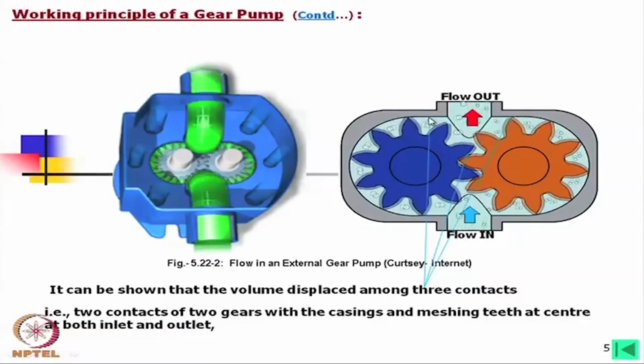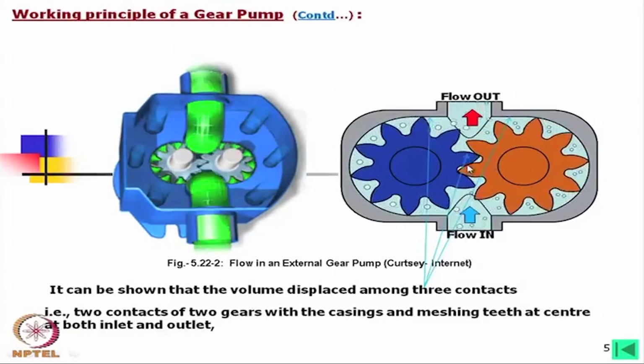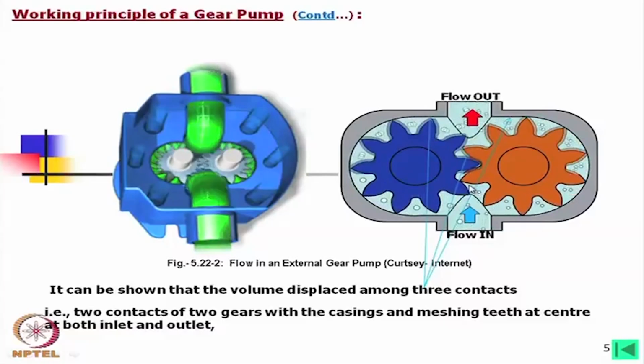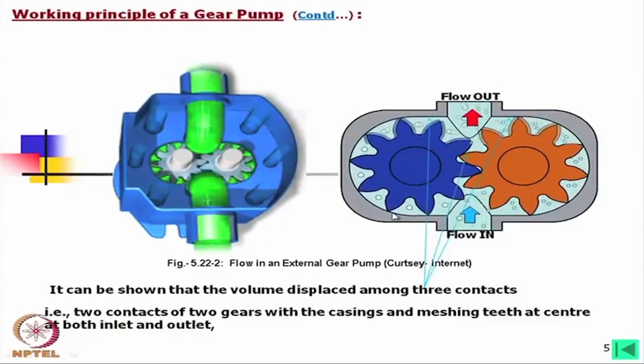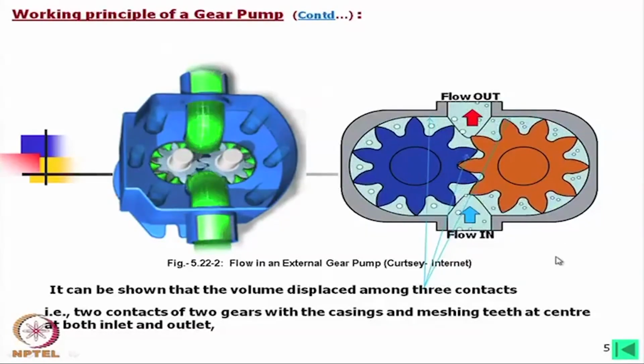So, one chamber means just consider the instantaneous last teeth in contact on this side and this side, and the contact point here. So, this is the compression chamber, and similarly the suction chamber is with this contact point here and the first contact point coming to the wall, and on this side the first contact coming to the wall. Okay.